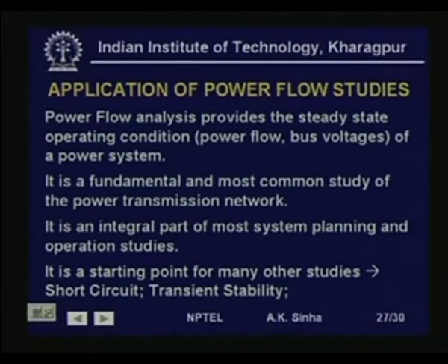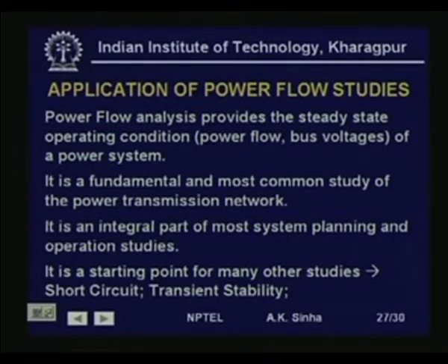Now, we will talk about the applications of power flow studies. What are we doing in a power flow study? Basically, we are trying to find out the steady state operating condition given the loads and the generation at different buses. That is, given the real and reactive power injections at various bus bars, we find the voltage phasors at the different bus bars. That is, voltage magnitude and phase angle at different bus bars are computed using the power flow method.